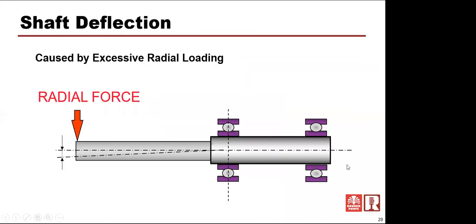leaking. If we were to look at the shaft being here, when we start getting off on that curve one way or the other, we get a radial force that causes that shaft to bend, to deflect one way or the other. That's why the Hydraulic Institute standards say we should operate between 50% and 120% of BEP to try to minimize that shaft deflection.